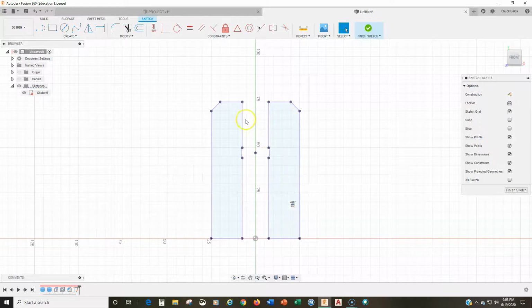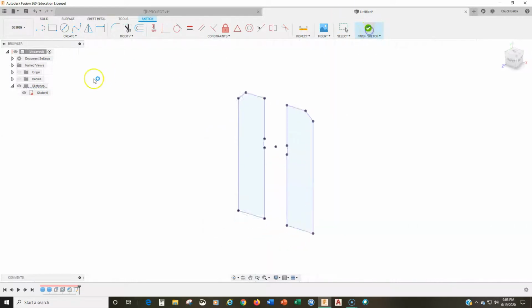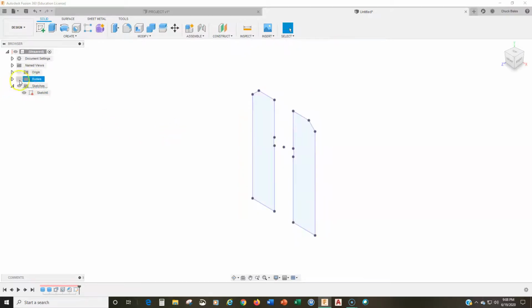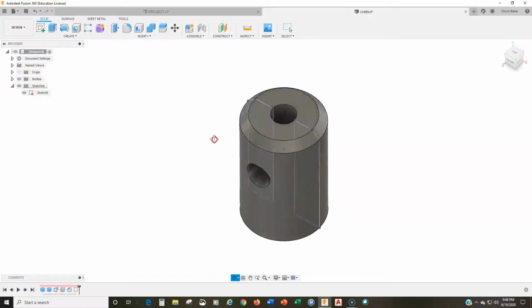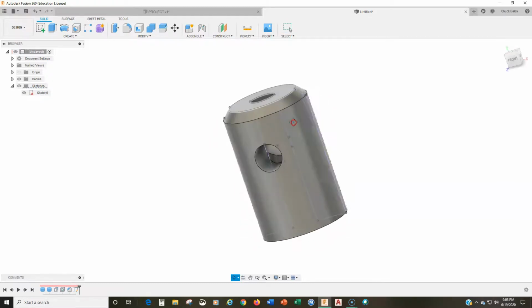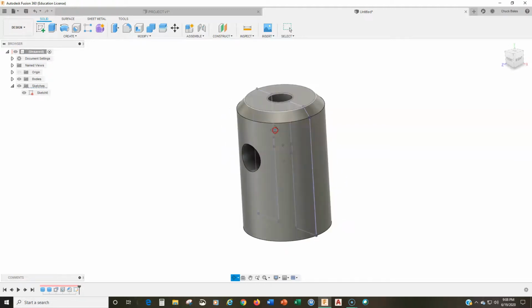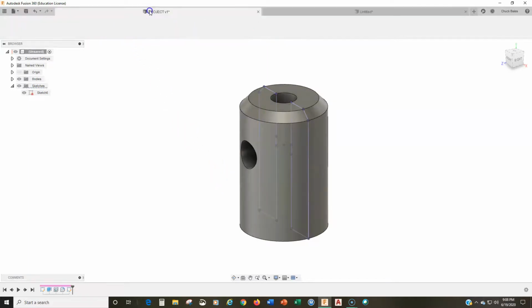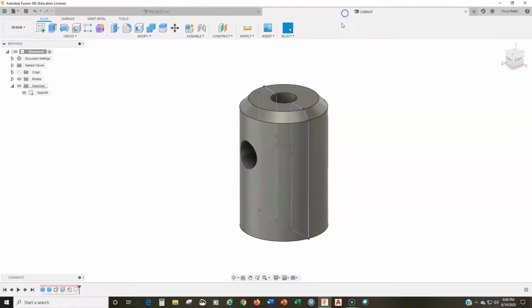Okay, and you can see that I had a hole going down the middle. So let me show you what geometry I had there. Let me turn on that. So you can see here that I had a hole going through the whole object, both vertically and then a horizontal hole. So it projected the edges onto that, or correctly, it intersected the edges. So there is a slight difference between intersect and project. There are cases where it would do the same thing.